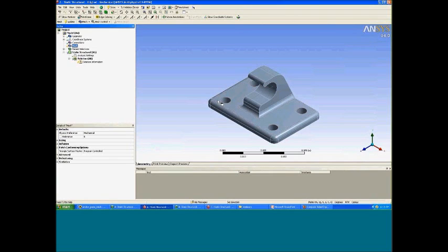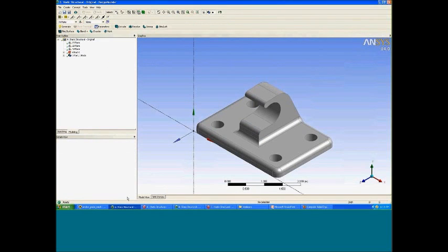And often this is important, particularly if you have complicated CAD parts where you're slicing and dicing and you may have small features that you miss. Ultimately, it's more important that Workbench Meshing thinks it's sweepable rather than you, and it can help you diagnose where you have difficult geometry. So let's go back to Design Modeler, and what I'd like to do is show everybody how I would go about creating a brick mesh with this part.